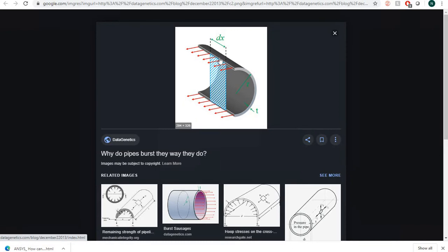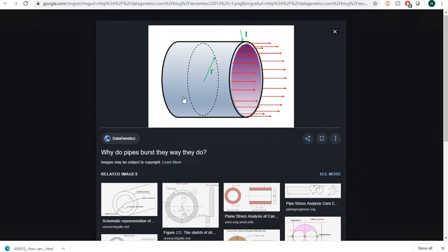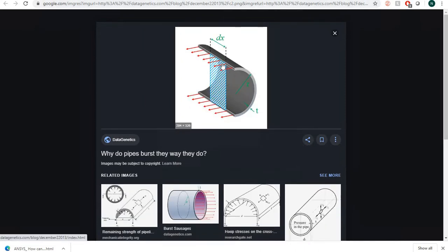It's not good to have this kind of cross-sectional area for a circular kind of pipe, because I told you at the beginning there will be errors due to the no slip condition near this cross-sectional area because of this curved path. If you want to analyze a circular cylinder, it would be a good option if you have an external flow. You can take a cross-section area like this, and you will not lose any properties or influence.